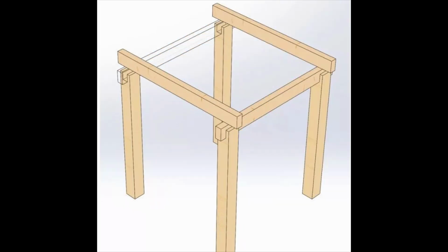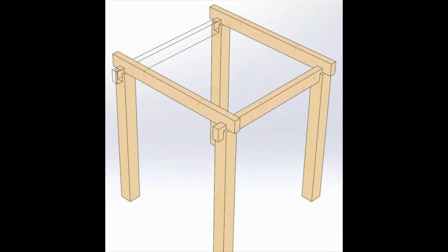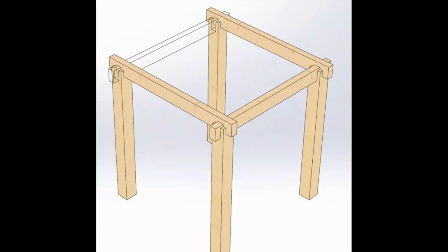Then they thought of digging a groove on the column and then placing the wooden beam, so that the sliding in one direction can be controlled. The connection between wooden beams also uses this mortise and tenon structure. According to the terminology of building structure, it is called adding constraints in one direction. Because they are all main beams, the load needs to be transferred directly to the columns instead of passing through another beam. So the wisdom of the ancients opened more grooves and adopted this mortise and tenon connection method.